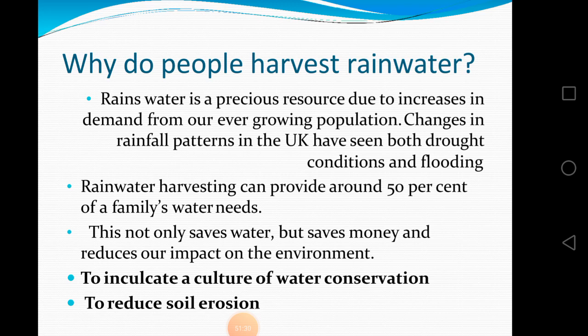We have to see the geological patterns of the location, especially watershed basins. So we have to see the soil patterns, geological patterns, and soil thickness. All these we have to see while designing appropriate rainwater harvesting structures, especially for groundwater recharge. For example, if you see the hydrogeological map, hydrogeology changes depending on the location, so rainwater harvesting recharge will also vary. Then the recharging rate also varies.